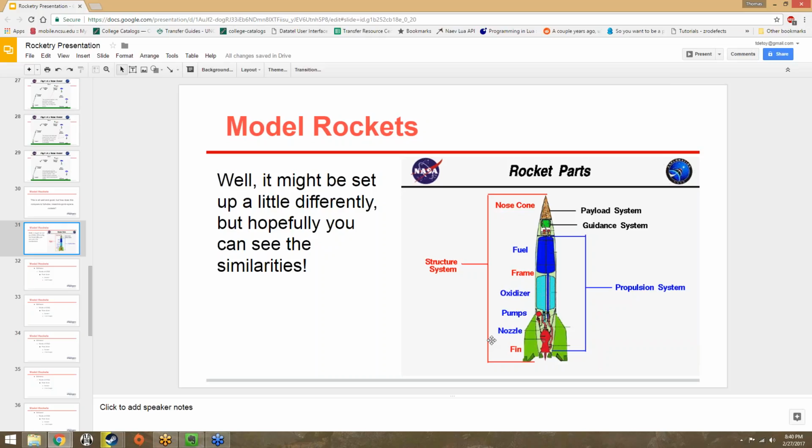But yeah, so solid rockets you generally can't turn off once you've turned them on. Liquid rockets you can. Solid rockets just go until they run out of fuel. Liquid rockets you can reduce the mixture, change the mixture, turn it off entirely. Liquid rockets are generally much easier to stick a vectored thrust nozzle onto, so you could control it much more easily.